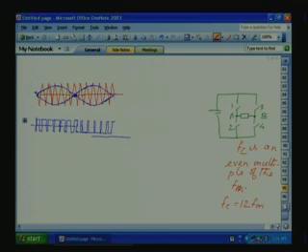That is for leg A. So in the PWM pattern, these are the portions during which the top switch is on, and the bottom switch is on. You can see the width slowly increases in a sinusoidal way.